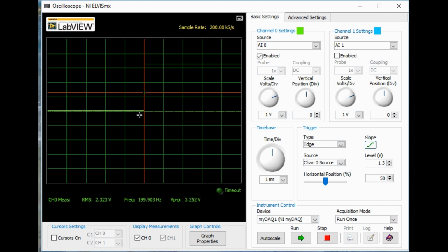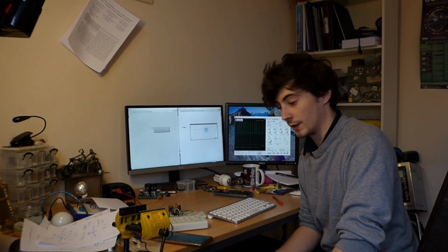But if we put a gate resistor in there, it will just slow the turn on time a little bit. It will get rid of this ringing. It will increase switching losses a little bit, but it will reduce all the ringing. Okay, thank you guys. So that's all there is to it.